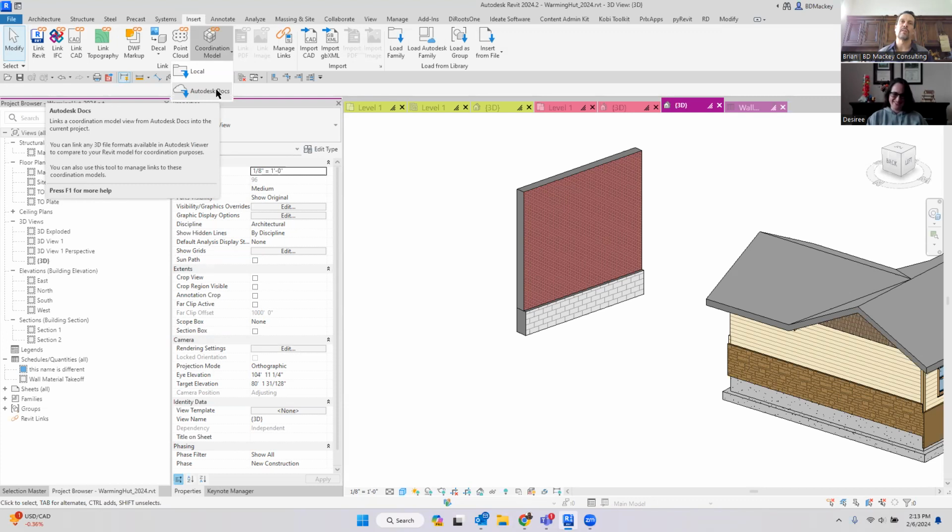Yeah, and then Simon is saying if that came in as a direct shape, they're extremely heavy, and he's seen model corruption. I think that depends on the direct shapes coming in, but there's lots of things that will trigger that direct shape thing. Like an IFC file will do that too. Yep, if it's an unrecognized object. So yeah, hopefully that answers your question.